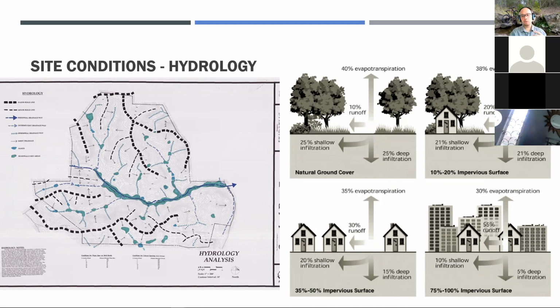Land development may also negatively impact groundwater quality. Now, this is especially problematic when local groundwater is a source of a community's potable water. So efforts must be made to ensure that an on-site wastewater treatment system and stormwater runoff don't contaminate these local community wells.